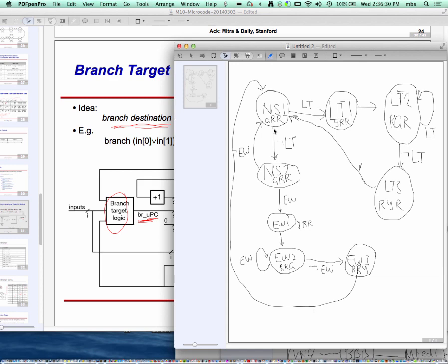This version, I don't know whether it's improved or not, depending upon the example. One may be better, the other may be better. It's always a trade-off between the program size versus the other. They're just different ways of doing it. And a lot of times you don't have control over it. The rest of the stuff has already been designed for you. Micro instruction format is fixed. All you are doing is writing a program. On the other hand, in early stages, when you are designing the chip or the system, then you are designing the micro instruction also, in which case you can have more flexibility.